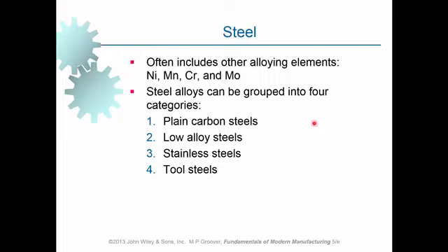And tool steels, what are they? The types of steels that are known for certain properties, and those are hardness, of course, very hard indeed. Tool steels must be very hard because they are the ones to be used in order to cut so many materials, including some types of steels, softer steels. And they have to be very good in terms of resistance to wear.